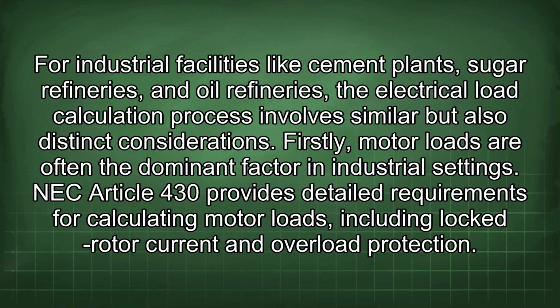For industrial facilities like cement plants, sugar refineries, and oil refineries, the electrical load calculation process involves similar but also distinct considerations. Firstly, motor loads are often the dominant factor in industrial settings. NEC Article 430 provides detailed requirements for calculating motor loads, including locked rotor current and overload protection.